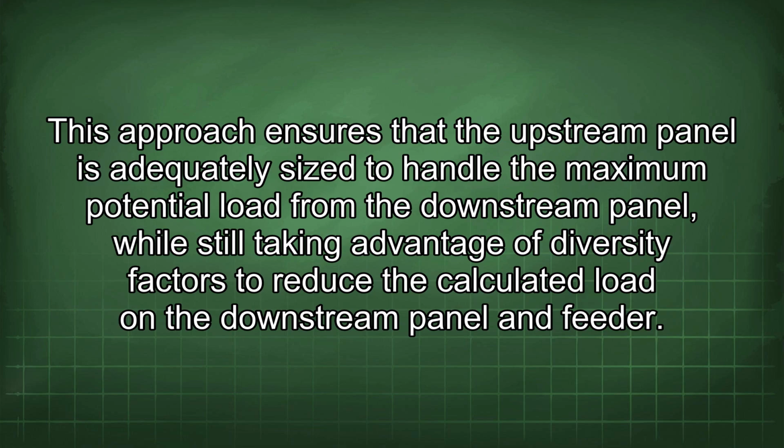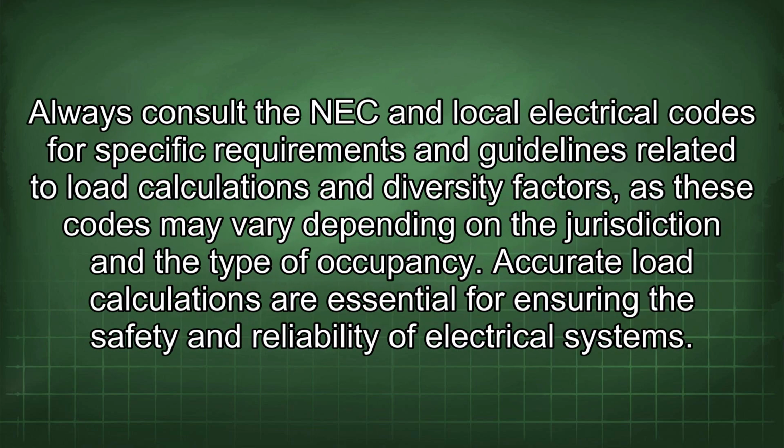This approach ensures that the upstream panel is adequately sized to handle the maximum potential load from the downstream panel, while still taking advantage of diversity factors to reduce the calculated load on the downstream panel and feeder. Always consult the NEC and local electrical codes for specific requirements and guidelines related to load calculations and diversity factors, as these codes may vary depending on the jurisdiction and the type of occupancy.